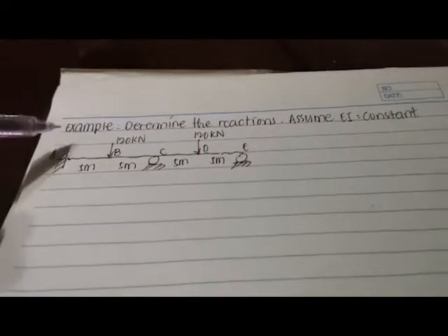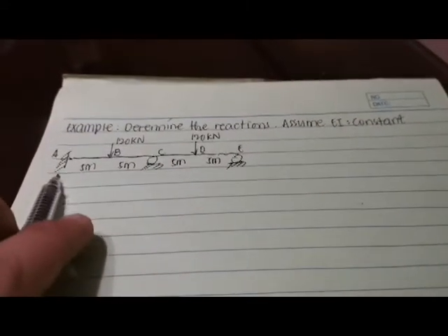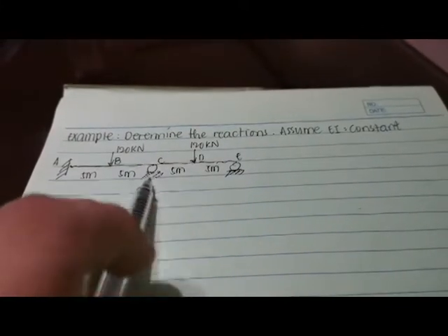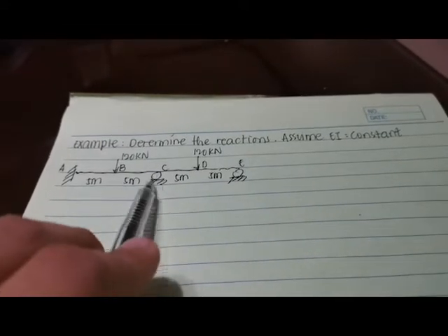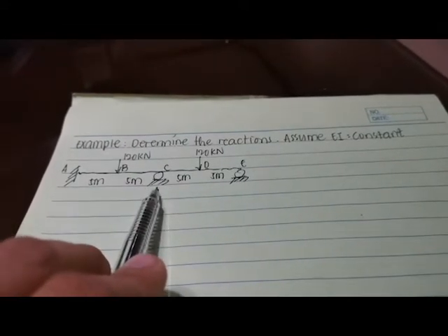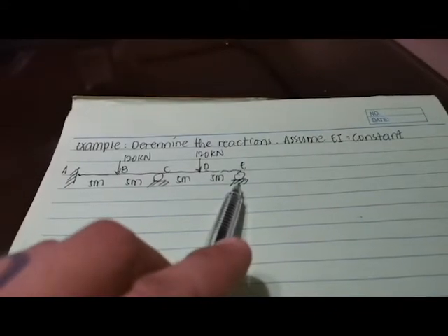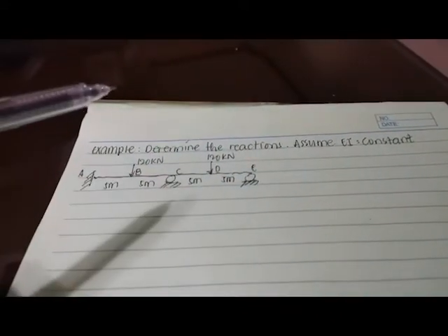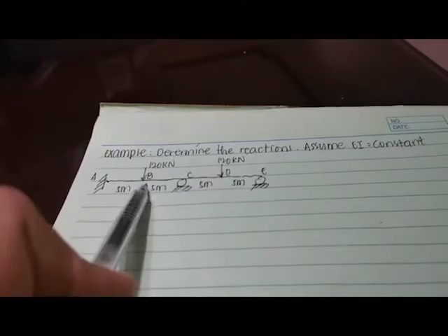So let's consider this example. This beam is similar to what I've shown you earlier. We have a fixed beam on the left. Let's say this is your point A. And we have an internal support at point C, which is located in the middle of the beam, and at point E on the rightmost of the beam. We have two concentrated loads on each midspan, denoted as points B and D.